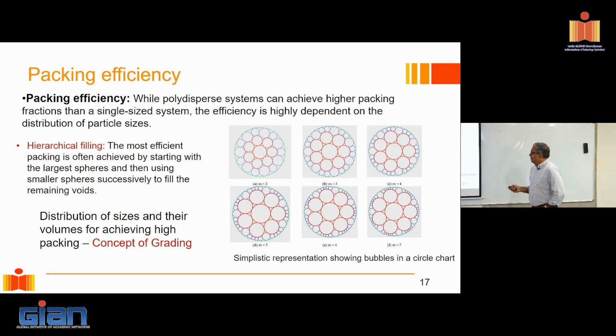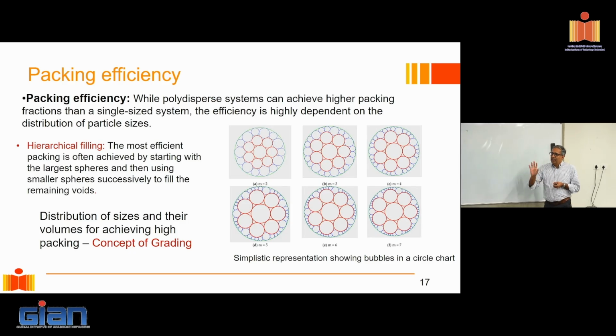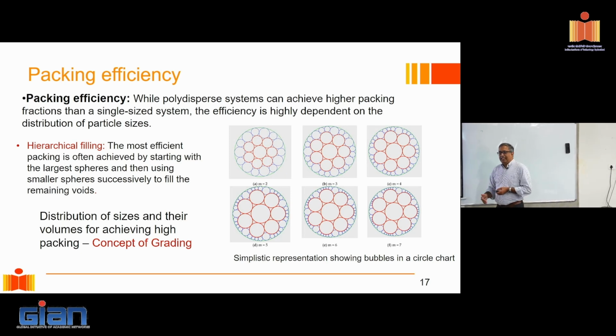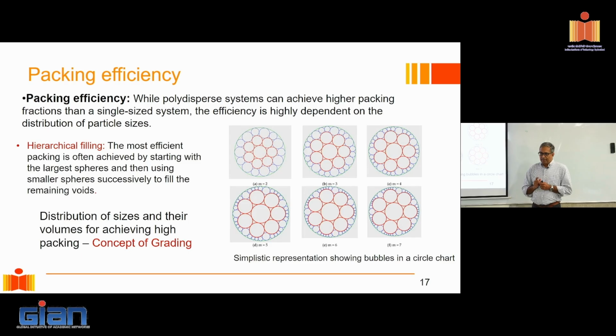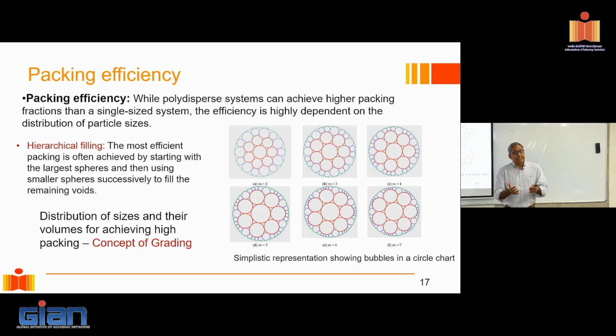So I have to make sure that my aggregate sizes are all available in the right proportion. And that brings us to this concept of grading. If I have aggregate available in the right sizes, in the right proportions, then I call it well graded. Now, what do I expect from a well graded aggregate? I expect that it would pack well.